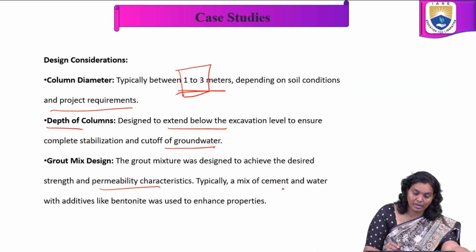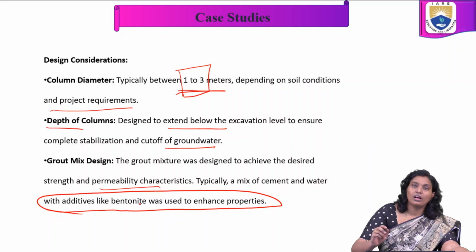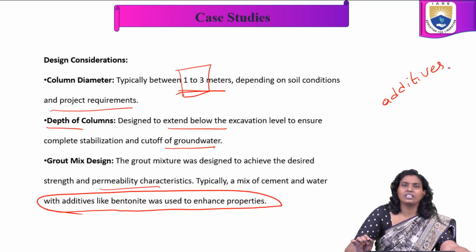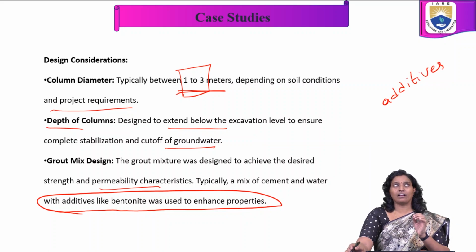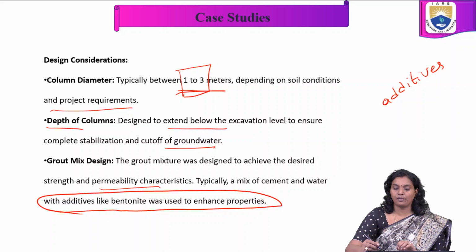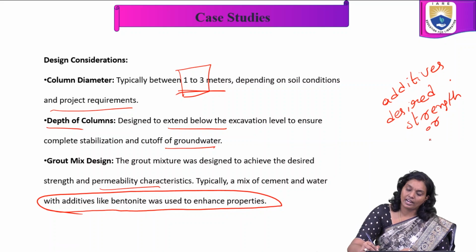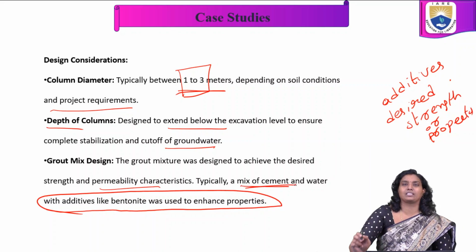typically a mix of cement and water with additives, which have various properties that enhance the mix. In the grout mix design, we choose the mix according to how we get the desired properties, the desired strength and permeability.